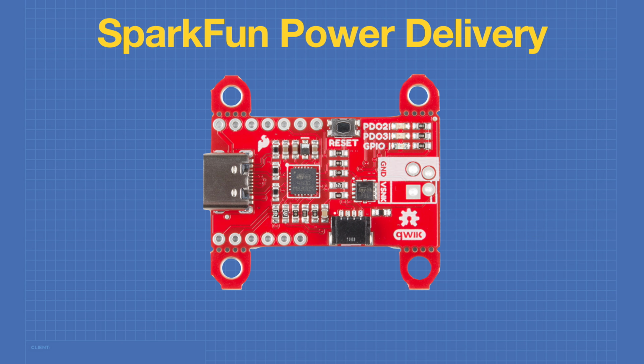Now here are the connections on the power delivery board. We can see a USB-C connector for the power input, and a quick connector on the bottom for easy connection to a microcontroller. On the other side, we have ground and VSYS, and these are both available as pins and a terminal strip solder area. This is the output power from the board.